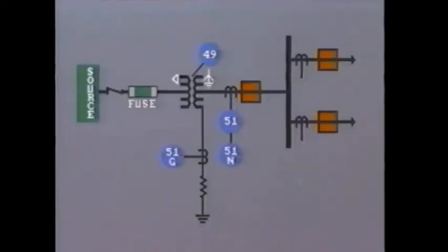Here is a typical protection arrangement for a distribution transformer feeding a small industry. Once again, the primary is delta connected and the secondary Y grounded. The basic protection is provided by overcurrent relays. A time overcurrent relay is installed on the outgoing secondary leads to protect the secondary winding against overload by tripping the secondary breaker.